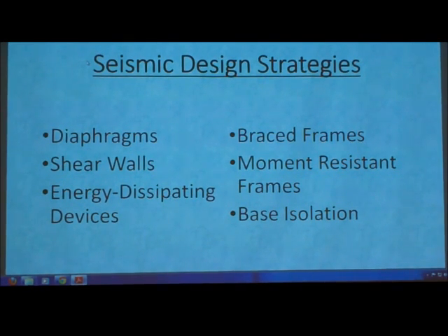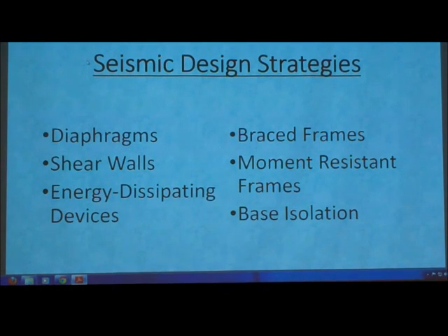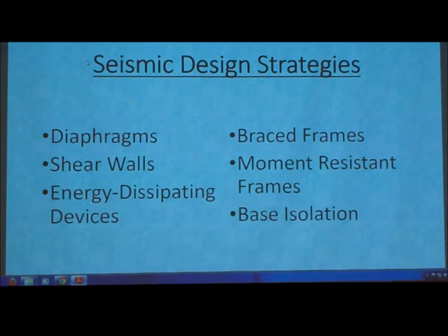And another thing that I thought was cool is something called base isolation, which is where you basically have it so your base and your building are separated. And so when these ground motions and forces start happening, your slab will be flailing, but your building will be staying vertically erect. This is something that is good to do, but you cannot use it for high-rise buildings because the building won't be able to act as rigid as possible. And the higher it goes, the more likely the moment can overturn it, and that will be a big problem.